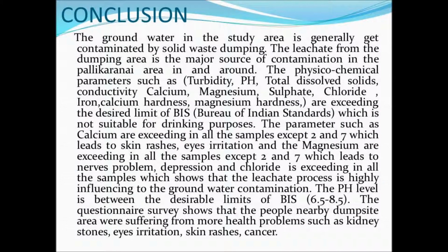Higher content. Our conclusion is that the study area is generally contaminated by solid waste dumping. These physicochemical parameters are exceeding the limit as per the BIS standard. Parameters such as calcium exceed in all samples except 2 and 7, which may lead to skin rashes, eye irritation and others. Magnesium exceeds in all samples except 2 and 7, which also leads to waterborne disease.